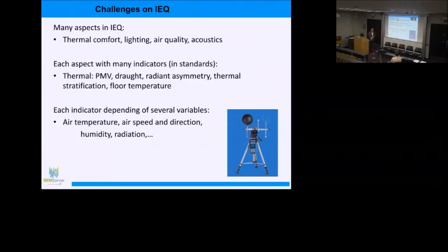I was thinking about it during the presentation. We have this displacement ventilation here, so the fresh air is coming from the floor. And as we have fewer people than in the design condition of this room, probably we're insufflating much more cold air into the room than we actually need. This air is getting accumulated here in the lower part of the room, which means that Tom, myself, and the first row will be exposed to more cold air than we expected and probably will face some thermal comfort issues. Now, this is not on the average thermal comfort sensation, it's more on the thermal stratification, would be the 4th item here.